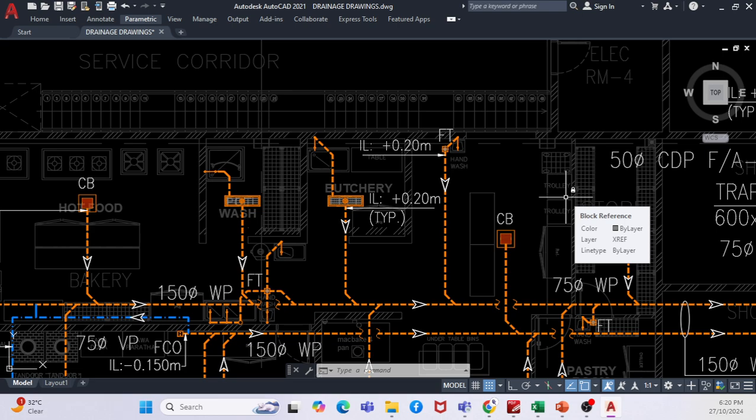First priority is the standard; second, you try to analyze the usage method, whether it is heavy usage or light usage. Based on the usage, you can increase the pipe size. If you increase the pipe size, the client will ask, if he is a technical person, why did you consider a higher pipe size? So you should have a justification, because of the higher usage, right?